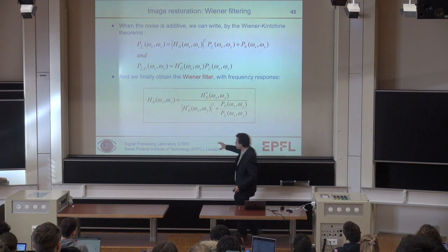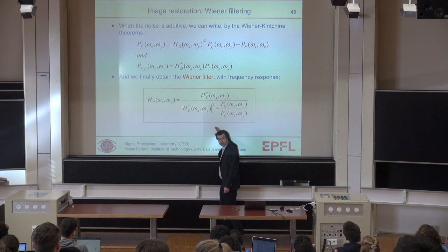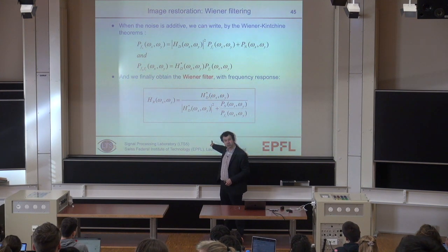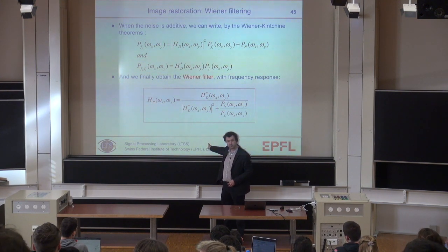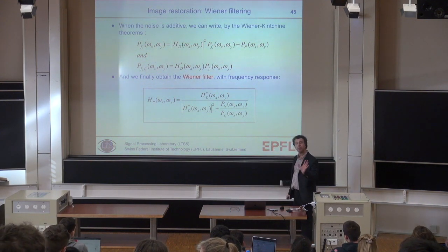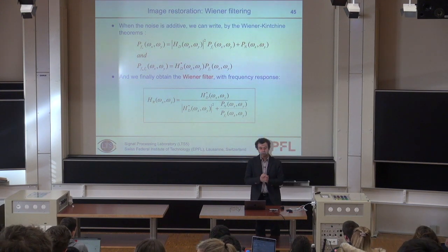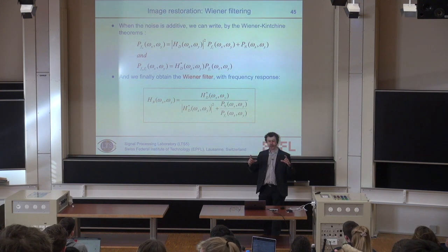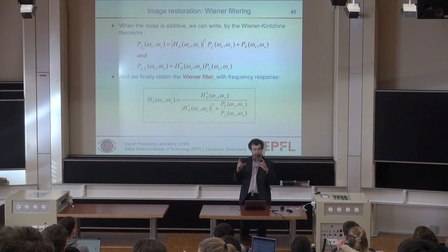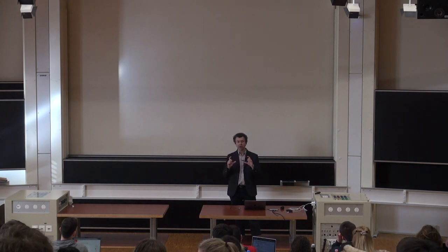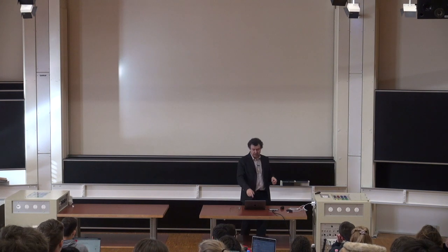But if you take a square here, and you see moving pixels, I mean random pixels, in that square, it's not because the board is dirty, it's because there is noise in the image. So estimating the noise is just one simple way to do it. I take an area in the image that is supposed to be uniform, you remove the mean, so you get basically only the noise, and you calculate the statistics.